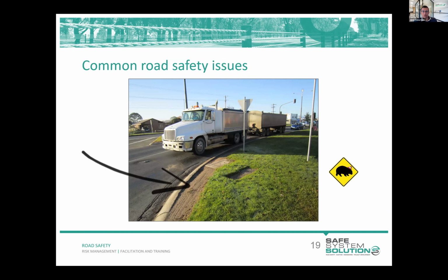When you're out on site, you might observe some signs such as tracking behind curb, which can point to an issue of a lack of space for the design vehicle. But that's not always the case. Often there might be an issue with speed compliance or a lack of delineation that results in vehicles traversing these areas that we don't want them to.